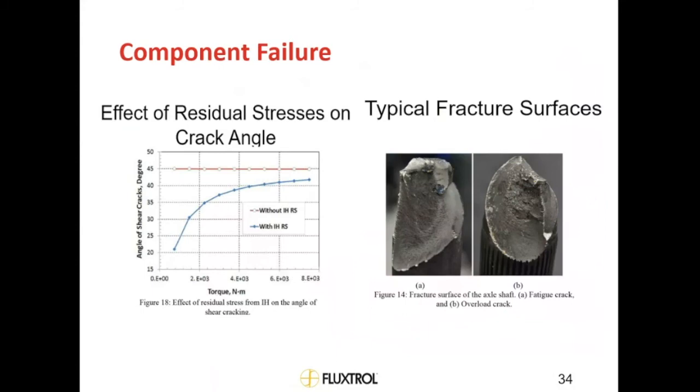When presented with these results, Greg Fett shared his work, which showed you can see visually in the pictures the difference in the crack angles between a fatigue crack and an overload crack, and neither one is at 45. There's definitely a much lower angle for the fatigue cracks and the overload cracks.